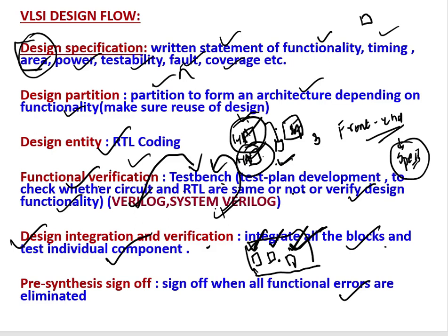It is like you want to make a register. Your register contains three flip flops: first flip flop, second flip flop, third flip flop. So first you write code for this one, then you write a test bench for this flip flop, and you verify it is okay. For the second you do the same thing, it is verified. You do the same thing, you verify.